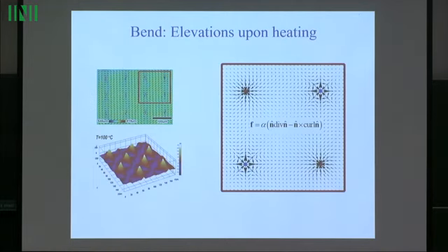You just plot the force F for different director fields with a known n. We know n and the gradients of n because we patterned it. We have this mask that specifies the dependence of n on the spatial coordinate. So since we know n, we can plot this active force. And you see here what it would look like for the liquid crystal elastomer patterned with plus-minus defects of circular type. You clearly see that in the case of +1 defects, all the forces are pointing towards the center, so the material will be going there.